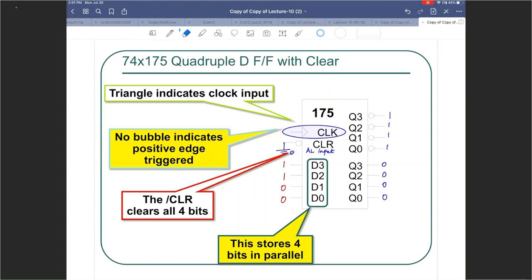You need to wait for the clock and the internal stuff. The internals are essentially related to the propagation delay for each D flip-flop. So if you ignore that, you still need to wait for the clock. What edge of the clock do I need to wait for? Positive edge of the clock. Yes. So I still need to wait for the positive edge of the clock. All right. So that's good.